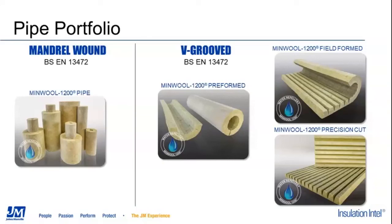The mandrel wound product, also known as molded pipe insulation, is prefabricated in the pipe format structure for small diameters. It will be a single cut, one longitudinal cut, and hinged on the opposing side. For larger pipe size applications, it will be either two clamshells or possibly quad pieces to cover the circumference.